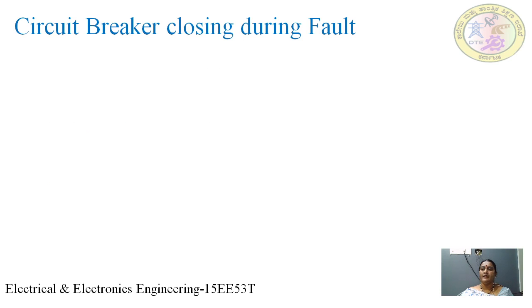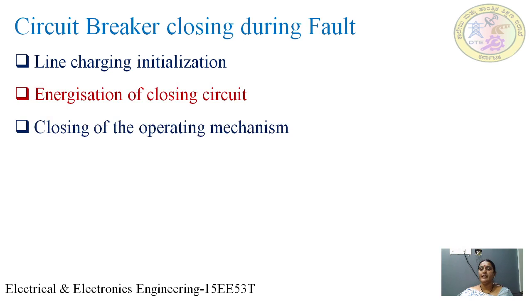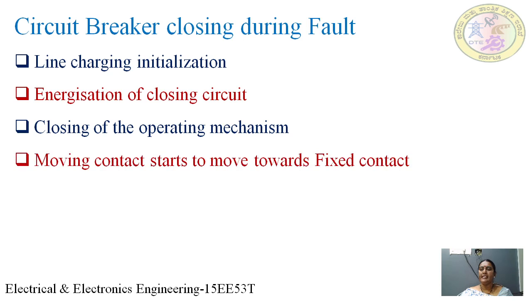Next, circuit breaker closing during fault. First, in that instant, there will be line charging initialization. Next, energization of the closing circuit. Next, closing of the operating mechanism.